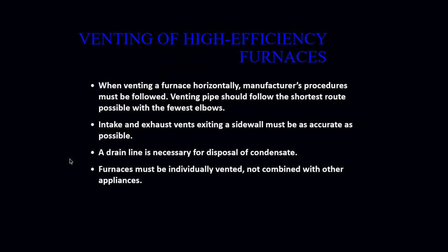When venting a furnace horizontally, manufacturer's procedures must be followed. Venting pipes should follow the shortest route possible with the fewest elbows. The trick of the trade is to try to keep your flue pipes as straight as possible using as few fittings as possible. Intake and exhaust vents exiting a sidewall must be as accurate as possible as well. A drain line is necessary for disposal of any sort of condensate.